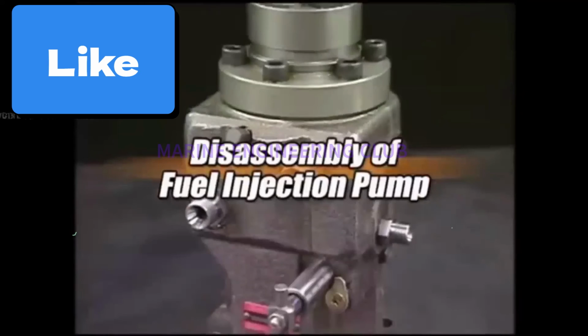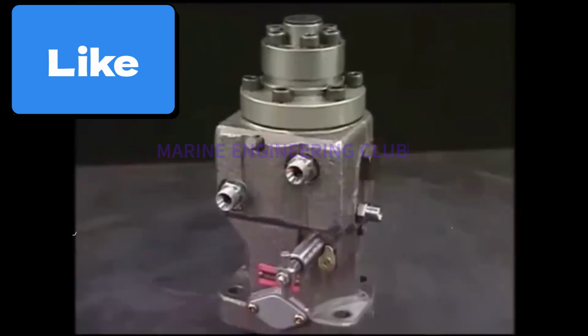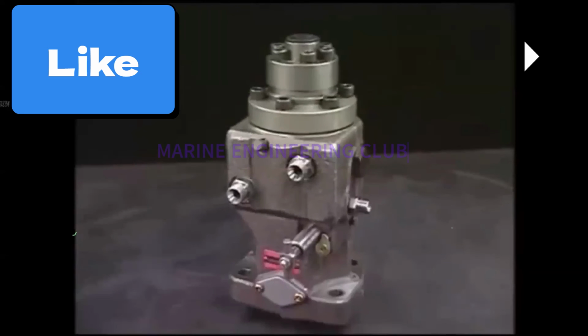Now we will disassemble the pump. Can you see here the plate down below, at the very bottom with 2 screws? This is for checking what? Sir, to check the beginning of injection. Okay, not on all pumps it will be given.